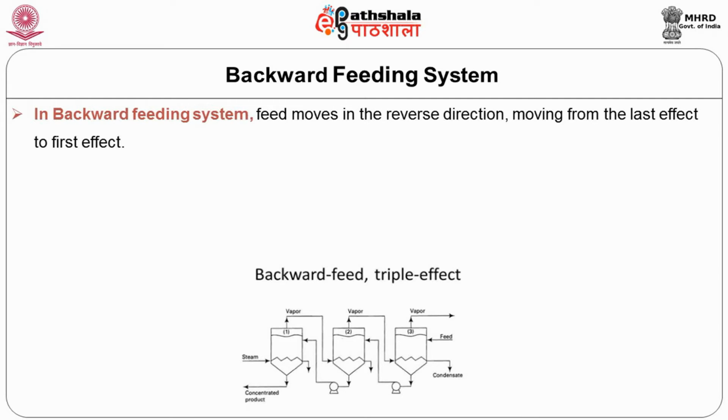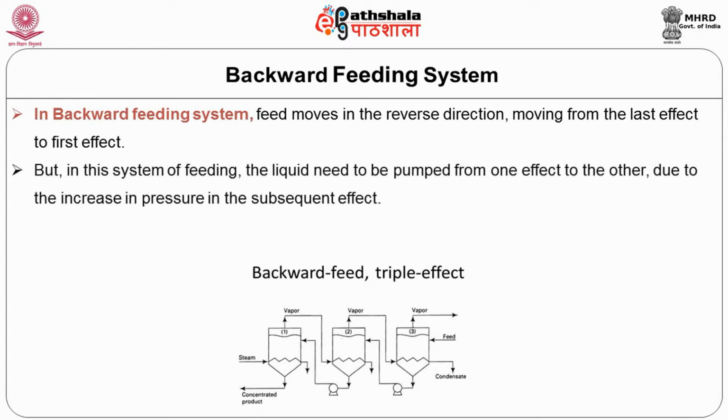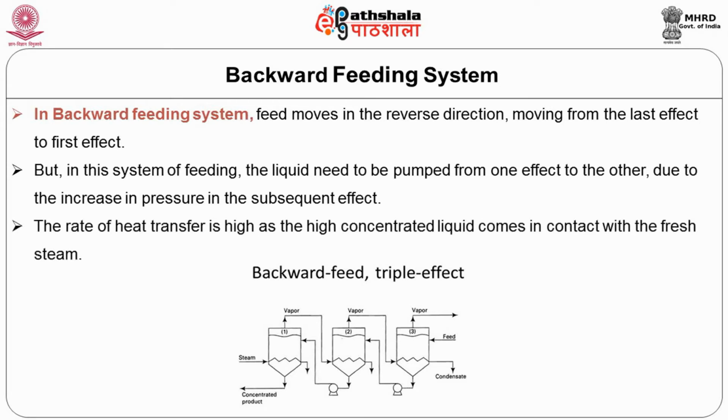Moving from the last effect to the first effect. But in this system of feeding, the liquid needs to be pumped from one effect to the other due to the increase in pressure in the subsequent effect. The rate of heat transfer is high as the highly concentrated liquid comes in contact with the fresh steam.